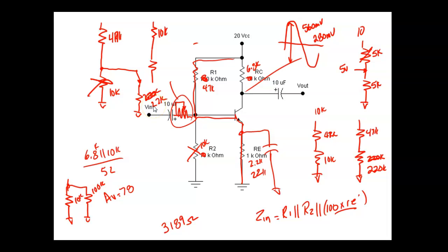So what was the value of the transistor at that point? The transistor is cut off. Well, we know if the output goes down, we can look at VC. Let's figure this. We know this resistor right here is dropping 1.7 volts. Sorry, it's dropping 1.05 or something like that.